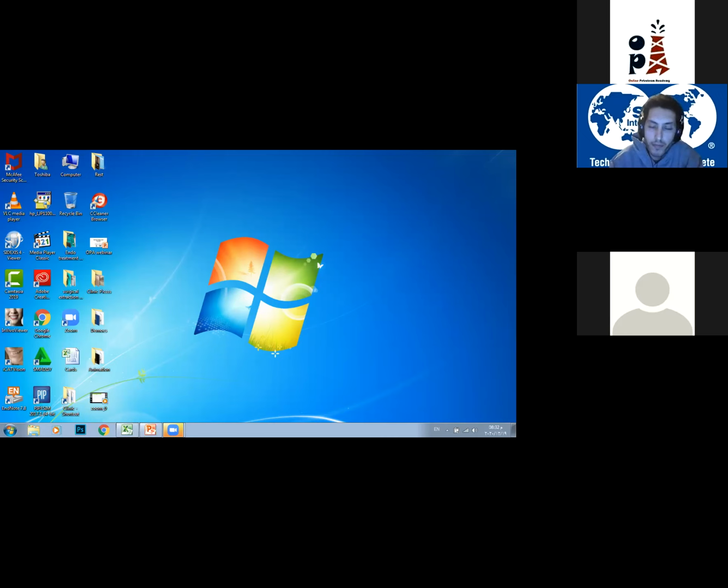If you compare valves or the gas lift system with ESP, for example, normally the ESP lifetime is like 2 years, 1.5 years, something like this. Gas lift is good, and one of its advantages is that it's flexible. It has a long lifetime. It's flexible, and as I mentioned, it's cheap. But the main problem is two things. First, you have a maximum drawdown you can inject. You have a certain gas lift, you have a certain maximum drawdown that you can produce, because you have many constraints: the high casing pressure constraint, the flow gradient. On the other hand, with ESP, you can produce with very high drawdown, with very high liquid rate. So everything you have, it's good and bad.